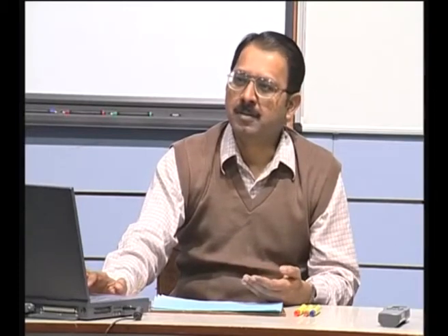Your question is whether FMS and CIM are different or one is a subset of the other. I would put FMS as a subset of CIM, because in a flexible manufacturing system you are actually looking at the manufacturing process and also the manufacturing system aspects and trying to integrate them. But CIM is broader; you are also trying to bring in the business functions, which are not a part of any FMS system. So, you can say FMS is a subset of computer integrated manufacturing, because in FMS you usually do not have business functions integrated, whereas in CIM you have this kind of integration.